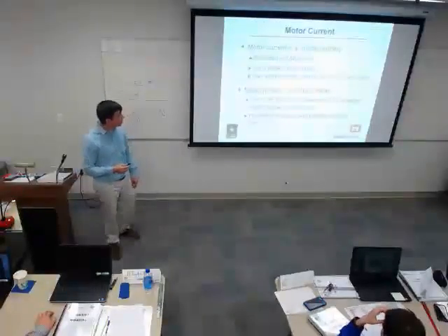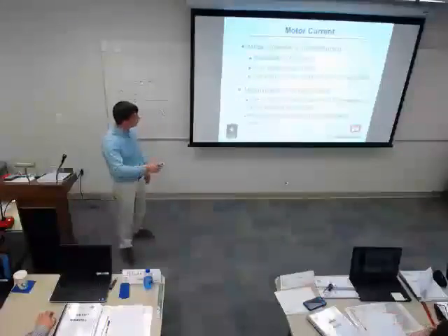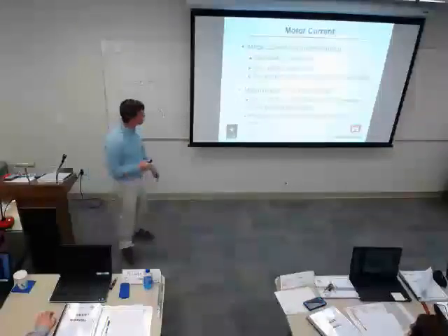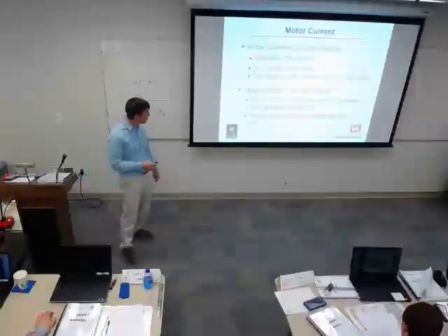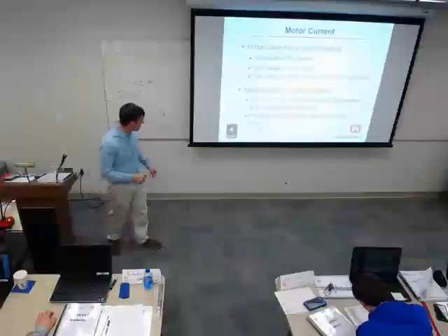All right, motor current. I've talked about that a good bit. Don't exceed the motor rating. We would use the clamp-on meter around each wire to take that reading and stay away from the service factor. I kind of got all this stuff. True RMS, make sure you use true RMS.